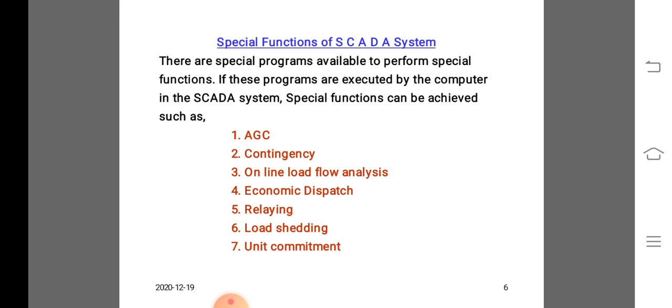On the SCADA system, there are two parts to the term SCADA, which we already saw in the previous slide. The SCADA is supervisory control, which indicates that the operator in the energy control center has the ability to control remote equipment. Data acquisition indicates that information is gathered characterizing the state of the remote equipment and sent to the energy control center for monitoring purposes.